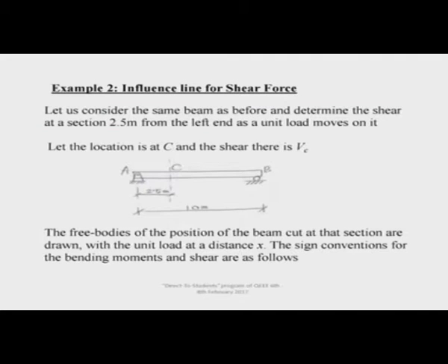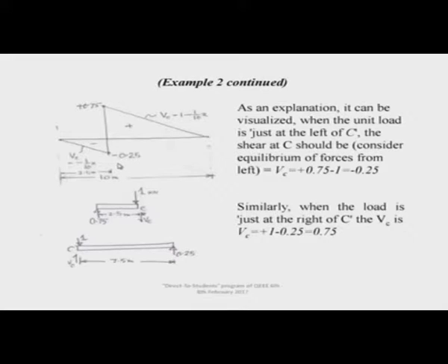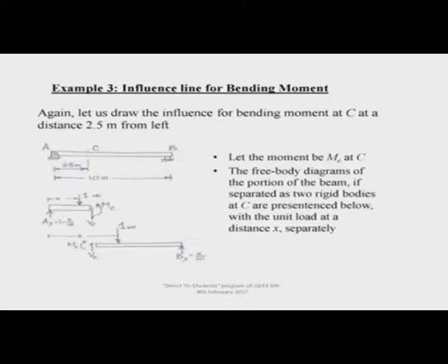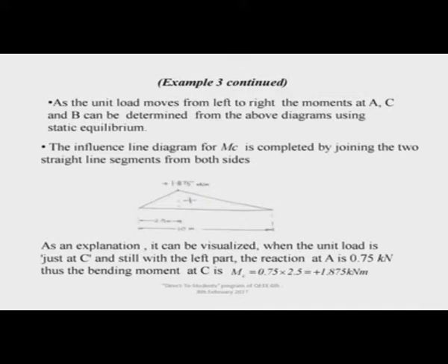Next is the influence line for shear force, what it looks like, and also a special emphasis on clearing your sign convention. I suggest you draw the shear force diagram for the load here, and understand the sign conventions as well as the difference between the diagrams. Next, we have drawn the influence line diagram for bending moment at particular sections. And this is the diagram.